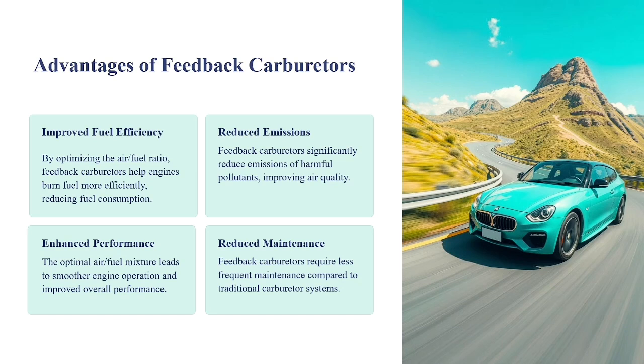Then reduce emission. Feedback carburetors significantly reduce emission of harmful pollutants, that is carbon monoxide and NOx, improving air quality through precise air fuel ratio control, minimizing excess fuel and oxygen.